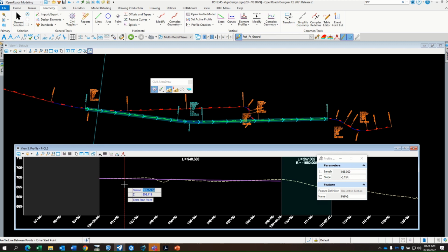We saw that in the beginning of the class when we pulled a 90 off of another line. We rotated that line, and that secondary line followed it, and it kept that constraint of 90 degrees, and that was my design intent, right?